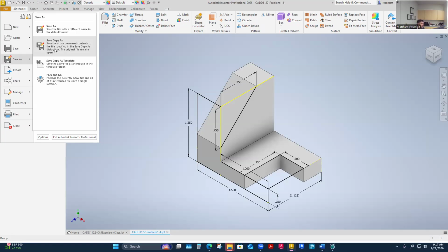Because if you're borrowing somebody else's part for your assemblies and you make a change to that part, and you've never made a copy of that part, their assembly is going to change too. This is the danger of all working from library parts. It's why usually the library parts system in a drafting environment will maybe have only one copy that you have to check out to make changes and then check back in. Even though you think you might have checked it out and you're making changes, if you didn't check out the part, none of your changes will be saved. So it's kind of this weird thing where we do protect our part integrity, but we can make copies of those and then explore them and not worry about messing up somebody else's model that this could be in. That's the other thing.